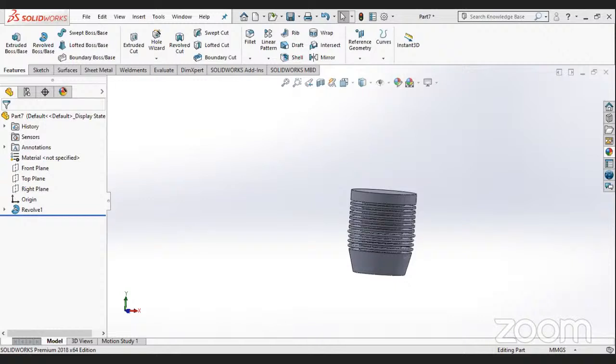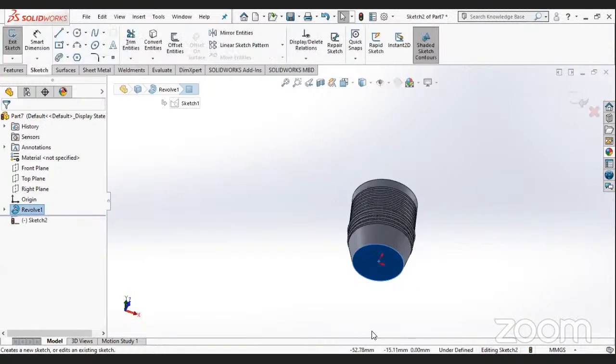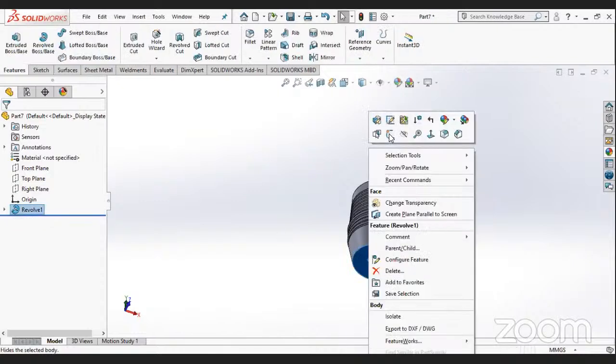You can see there is a hole inside here, of which the diameter is 54. So we'll quickly make a hole of 54 in the center in the down part. Please see the dimension. So the diameter is 54. We'll just select this, exit the sketch, select the surface and sketch on it.